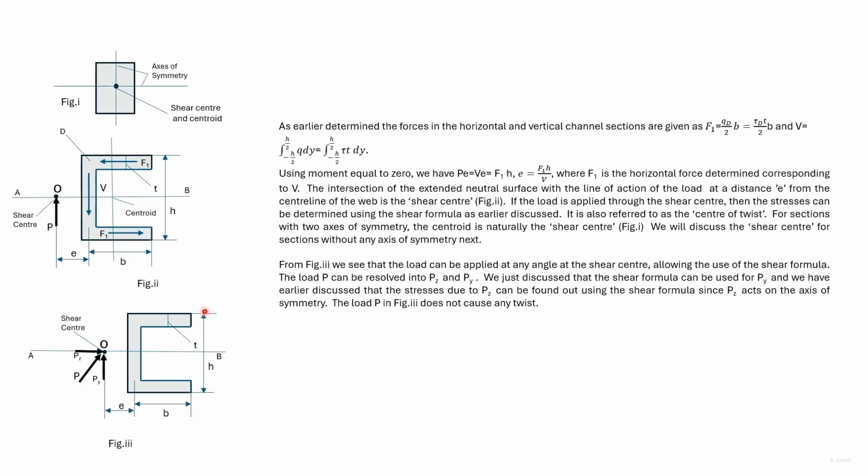For a section with one axis of symmetry, a force can be applied in any direction at the shear center. This does not cause any torque in the section and the shear stresses can be determined. We can resolve this force into Py and Pz as shown. We can use the shear stress formula to find stresses due to Pz, and we have just discussed that we can use the shear stress formula for Py. We can then sum up the stresses.